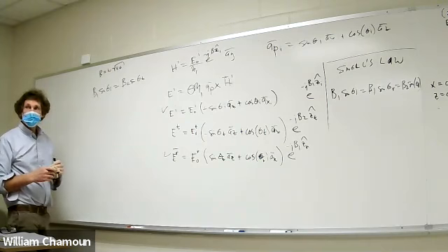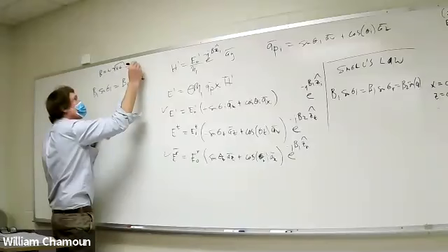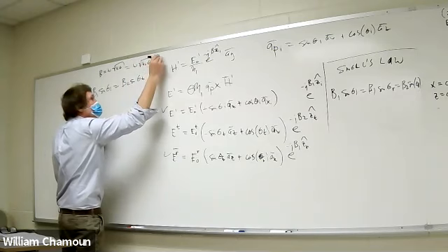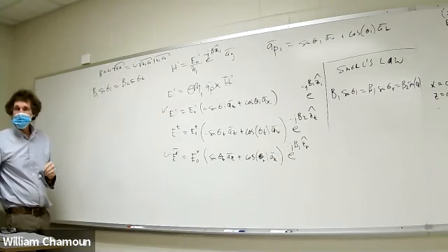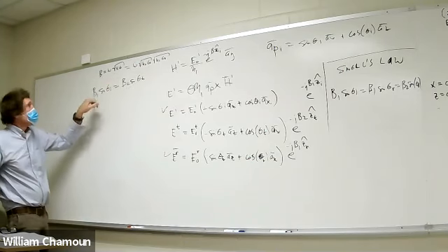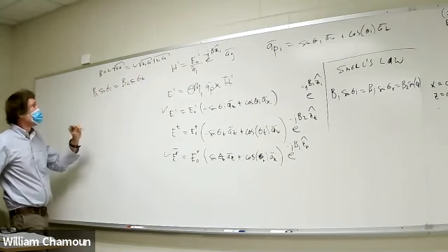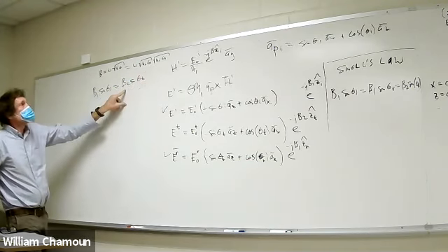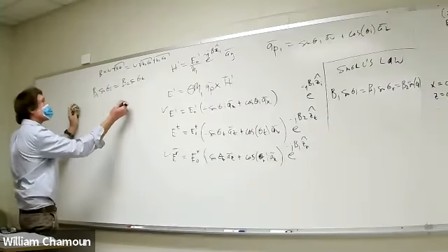We're going to make it even easier. If I take a look at this, this is really equal to omega square root of mu naught epsilon naught times square root of mu relative epsilon relative. I factored out the mu naught epsilon naught. You see how when I put beta 1 here with mu relative 1, epsilon relative 1, and equate it here with mu relative 2, epsilon relative 2, the omega and square root of mu naught epsilon naught cancel on both sides.